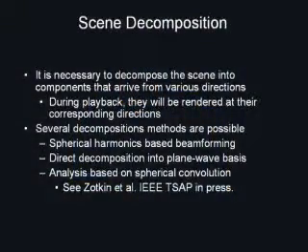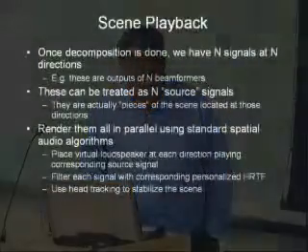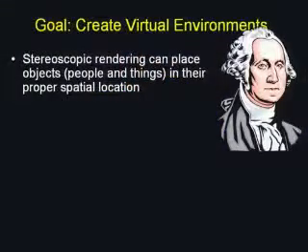Then we convert the sound field into a plane wave representation. So we know the plane waves which are impinging at that location. And now if I know your head-related transfer function, I can place you at that location by taking those plane waves and convolving them with your head-related transfer function. And this is the scene recording, scene playback. So as far as head-related transfer functions are concerned, these are the things.